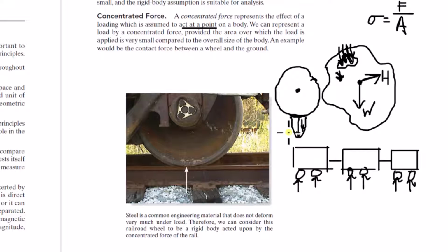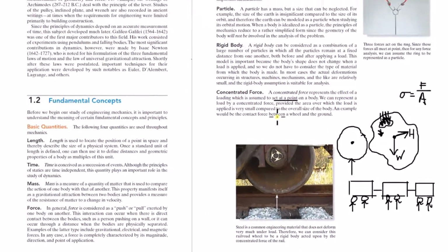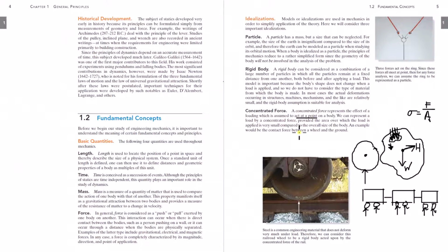If you were analyzing how the material in this region responds to the load, like how the material deforms in response to the load, you can't use a point force, because now you're getting into stresses, forces over areas. That makes no sense. But for solving for the general loads, like in a statics or dynamics problem, as long as that area of contact is small, you don't have to worry about it for that problem. And we'll see in this course when we're using that point force assumption.